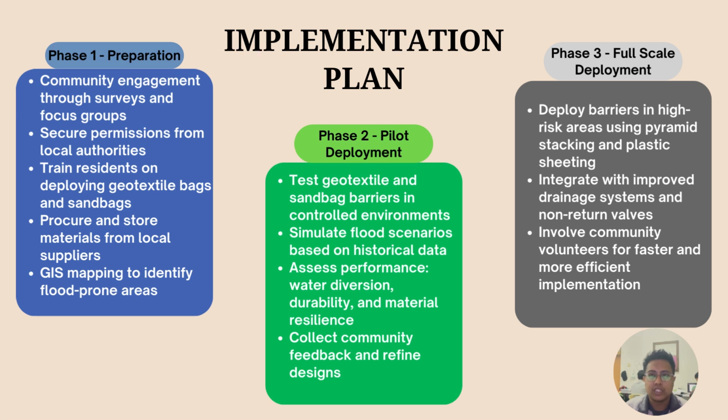Okay, for the phase 2 is pilot deployment. Test geotextile and sandbag barriers in controlled environment. Simulate flood scenarios based on historical data and assess performance, water diversion, durability and material resilience.